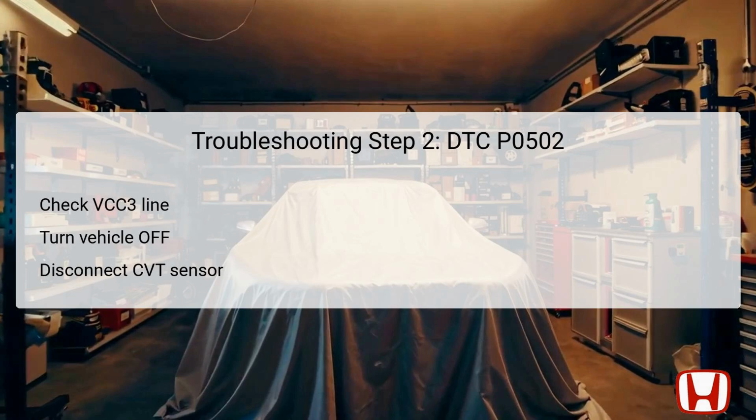Step 2 focuses on identifying the possible failure area, starting with the VCC3 line. The technician starts by turning the vehicle to the off or lock position to ensure safety while working on the electrical components. The next crucial action is to disconnect the CVT speed sensor's 3P connector, isolating it from the circuit for accurate testing. Subsequently, the ignition is turned back to the on position while the connector remains disconnected.